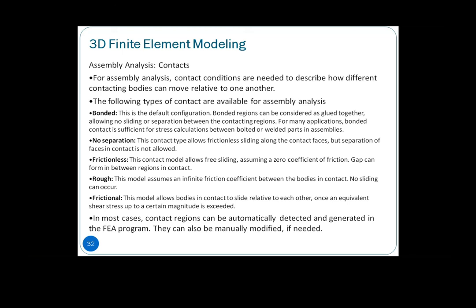Rough cannot slide. No sliding can occur because the surface is very rough. Basically it is an infinite friction coefficient, so no sliding, but it would allow separation. Frictional: if you know the coefficient of friction of that particular body, then you can set it, and it is allowed to slide, of course based on the coefficient of friction that you have set. So that is frictional.